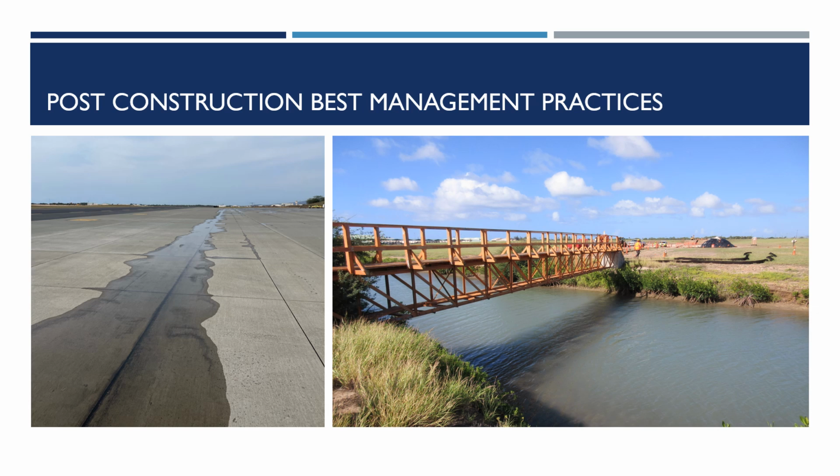Post-construction best management practices, commonly referred to as PBMPs, are permanent features constructed to treat potential pollutants. Development often results in an increase in impervious area and more stormwater runoff, and therefore a higher chance of pollutants contaminating stormwater, groundwater, and soil. The main goal of incorporating PBMPs is to reduce or eliminate pollutant discharges from the site after construction is completed. Projects will undergo review for PBMPs through the design review process on VOC.